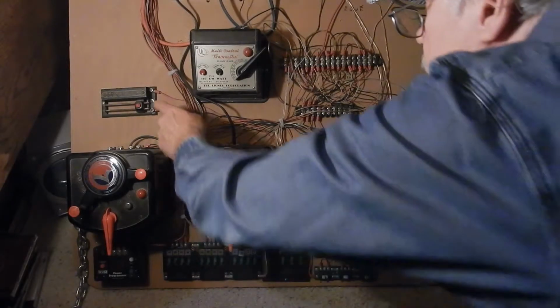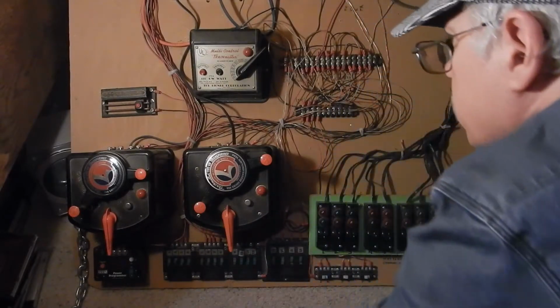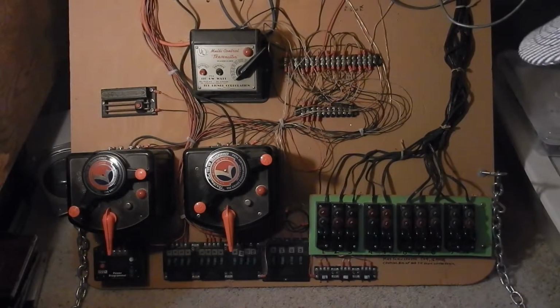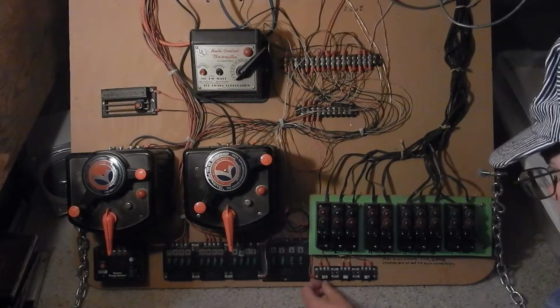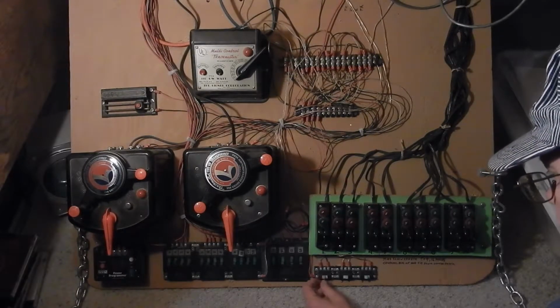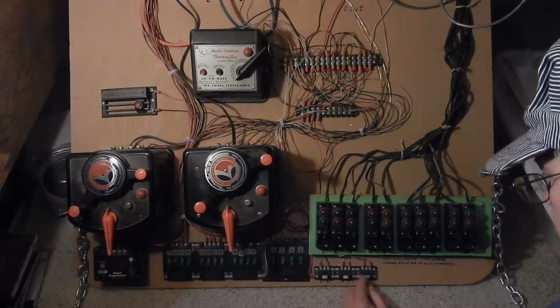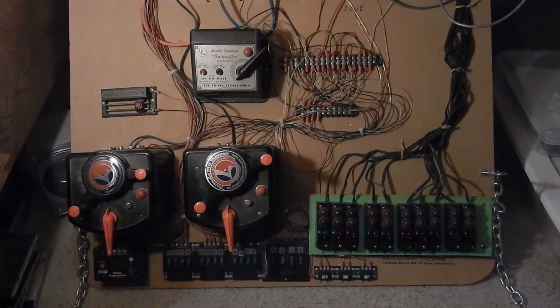This resistor here is used to reduce voltage to the switch tracks. The idea being to run them at the lowest voltage possible and still have them switch. My understanding is it helps preserve some of the contacts inside. The lower the voltage, the longer they're going to operate. And so far there's been no problem with those switch tracks. On coupler tracks, there's 6 of them, and they're down here. These are the controllers that we're using. Now, when you switch to this side, this is 1, 2, 3, 4, 5, 6. Okay, that's pretty much what we have for controls that's active right now.